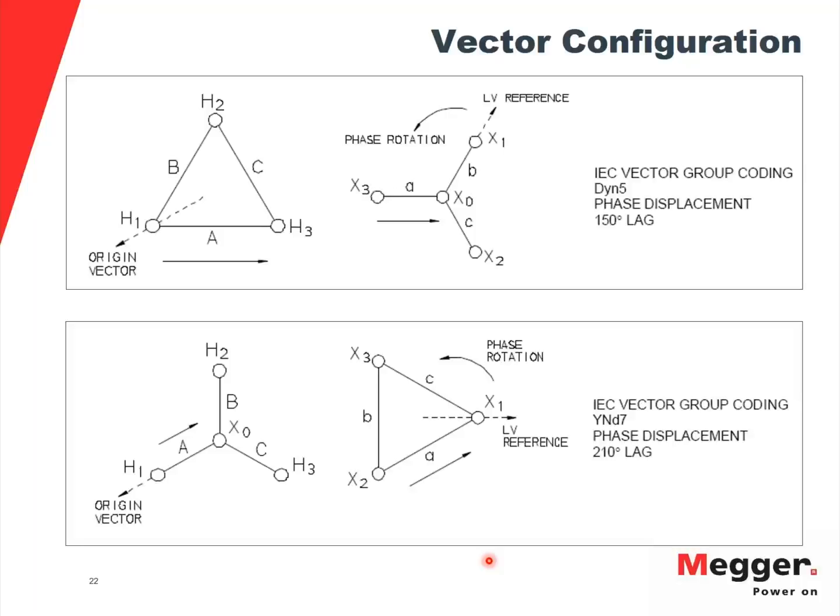Okay. Well, let's go back to the physics, right? When you are running a winding resistance test, basically you are giving an orientation to the magnetic domains of your transformer. By doing this, you're saturating the core. And when you have the core saturated, if you energize your transformer, what's going to happen is that you will have high inrush current. And you will generate especially odd harmonics here, especially you will have a big component of second harmonics that may trip your protection system, okay?